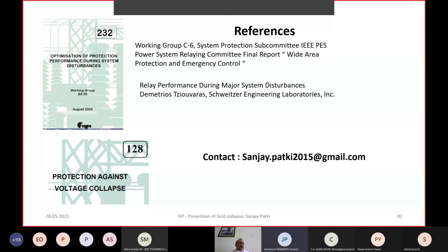No, it is basically the algorithm of the distance to fault measurement, which suppliers are more familiar with, because the distance to fault algorithm is different from the impedance distance calculation in the protection. And the way the X by R ratio, SIR, and the mutual impedance effect, zero sequence compensation are treated in the two relays, both are different.